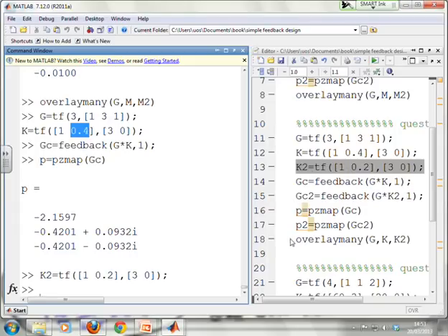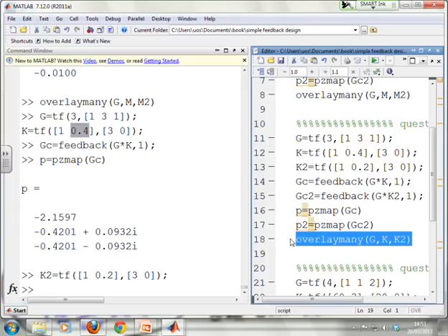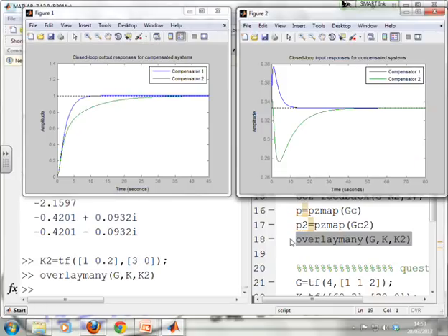Now, let's run the simulation and see what happens with both these compensators. So with the heuristic design, we have this blue plot, which is smooth, goes to the steady state, quite a good time constant, and there you can see the input. Okay, it overshoots a bit, but not enormously, given the steady state of a third. It's gone up to about 0.38. Now, when we halve the integral term, you get this green plot. Do you notice it's much slower, and the input undershoots rather than overshoots?